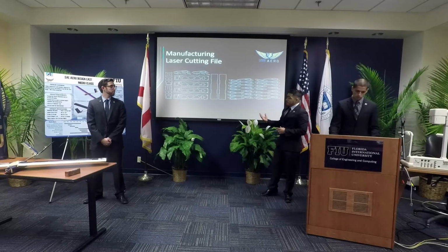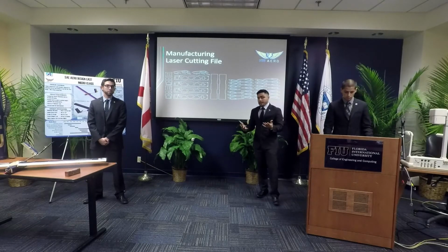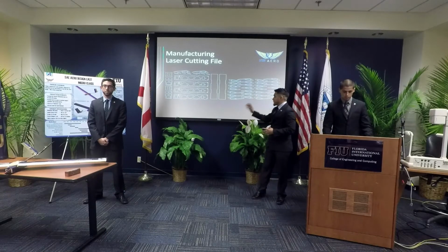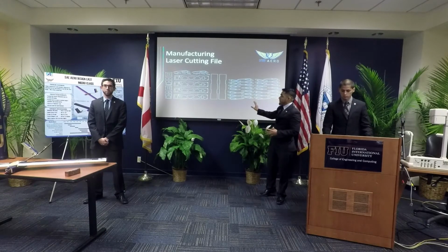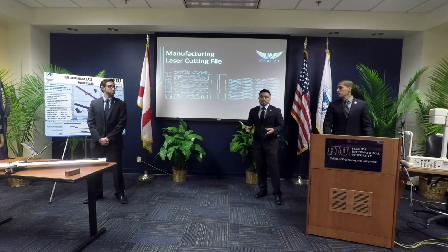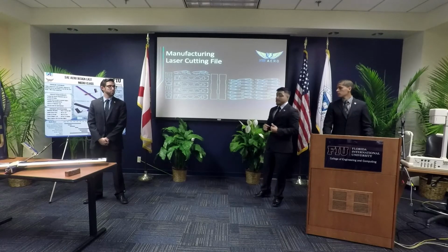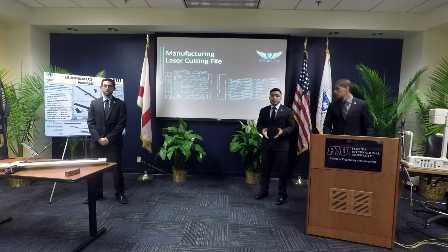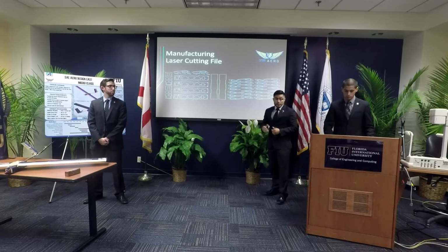So for the manufacturing, in any engineering application, you always want to consider manufacturing, and pretty much this is a basic layout that we send to our laser cutter. We try to integrate all our components into one sheet. This facilitates the laser cutting time, meaning we're saving money and we're also saving time for the guys to set up the files. Next slide, please.